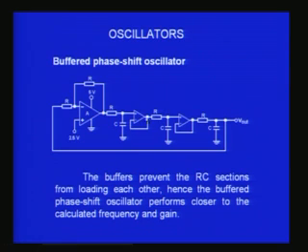For that I have used a unity gain buffer, which you know is a very good circuit to produce very high input impedance and very low output impedance with a gain 1, and therefore they only provide high input impedance here. It is so high that the reactive component due to C is the only contribution to the resistance here, and therefore the effect of all the rest of the things that is connected will not be felt here.